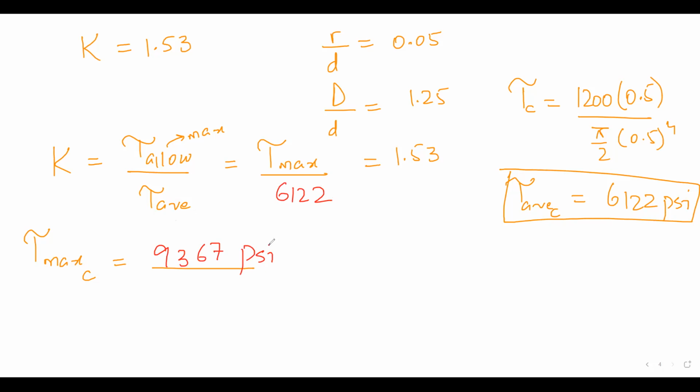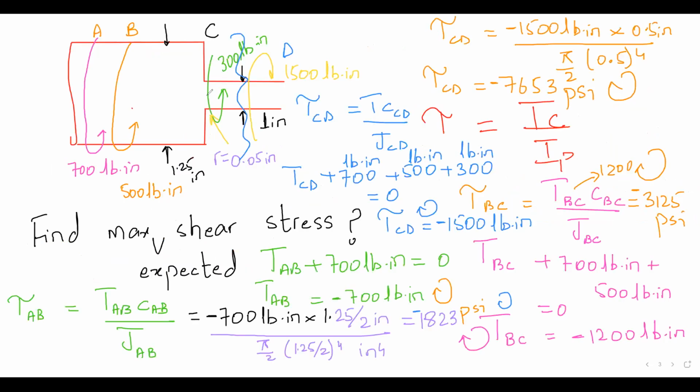So for those students who are saying what on earth just happened, let me try to explain. The problem is that you have a stress concentration here. When you have a stress concentration here, I cannot just cut from any place and take that torque. I have to take the torque, or talk about the shear stress, right next to this layer. Are you getting my point? If you are putting a torque here, it will have a finite distance from here. It cannot be glued to this one.